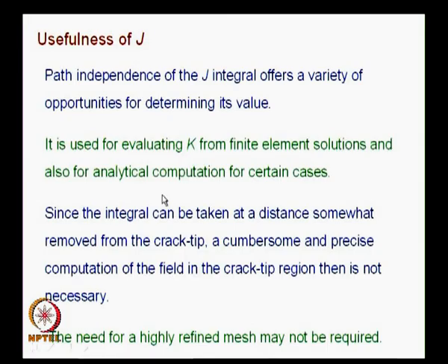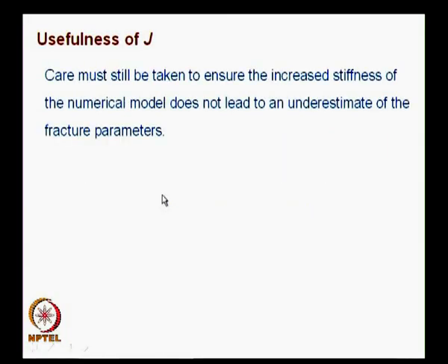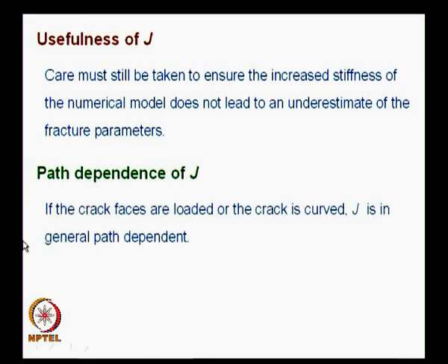Is it always so? You have path dependence of J. It happens if the crack faces are loaded or the crack is curved, J is in general path dependent. So, excluding these exceptions, you can find J is useful, and there is also a caution given.